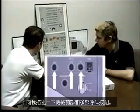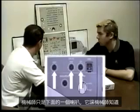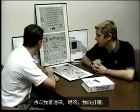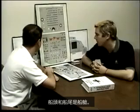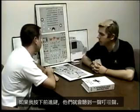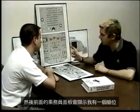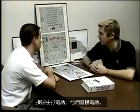Calls. Describe to me the mechanic, forward and aft call push buttons. The mechanic call is just a horn down below, and it lets the mechanic know that you want to talk to him, so he'll come over and talk to you. The forward and the aft are for the cabin. If I press the forward, they'll get a single ding, and at the flight attendant panel up front it'll say that I've got a cabin attendant call, and they're going to answer the phone.